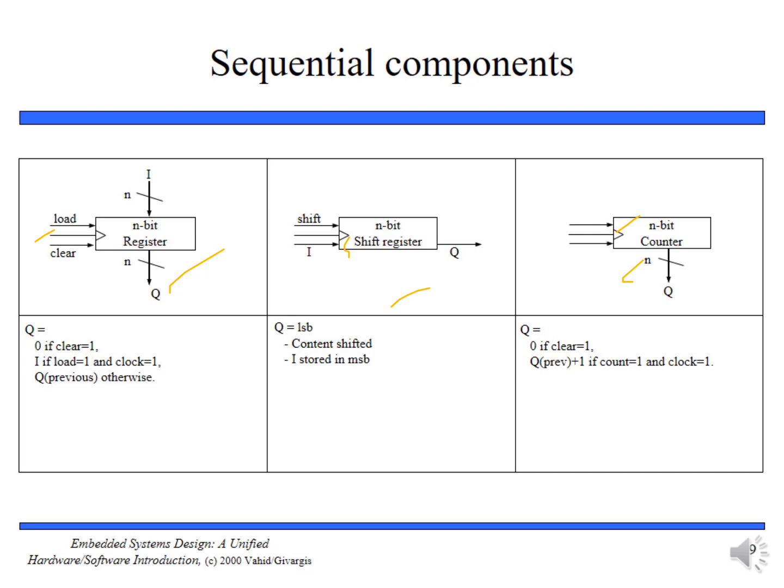To prevent unexpected behavior from signal glitches, flip-flops are typically designed to be edge triggered, meaning they examine their non-clock inputs only at a clock edge. So they are edge triggered, not level sensitive. They change their behavior when the clock is either rising from 0 to 1 or falling.